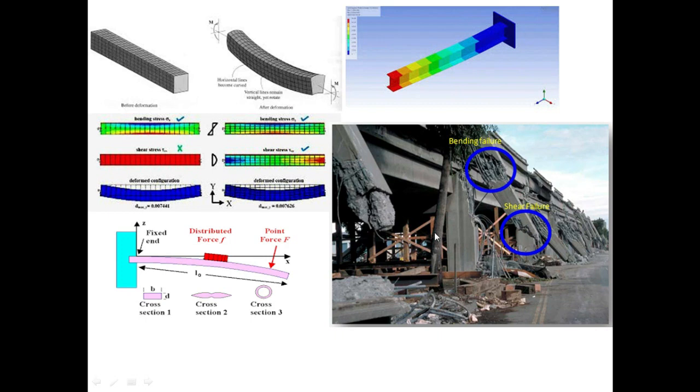So again, this is showing you the configuration of types of loads that can act on the beam. Definitely on the top, you can say moment is basically a load. Then again, they have given you an example of a cantilever beam. If you look at this cantilever beam closely, it is fixed to the wall here. So what we can assume is that it is a fixed support.